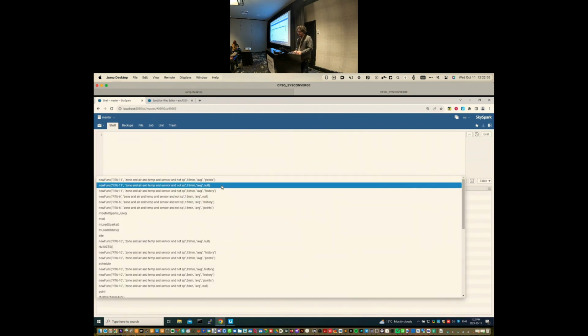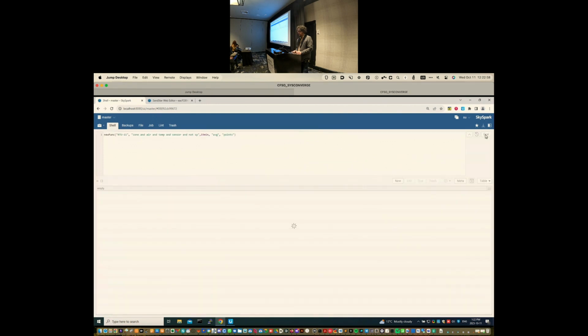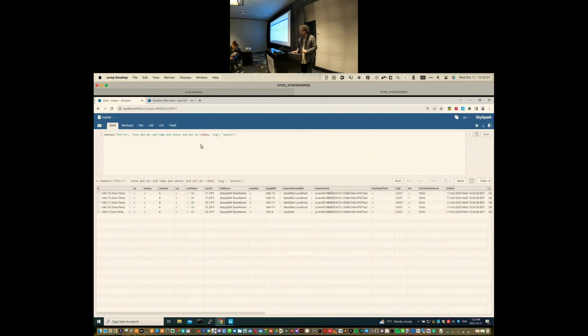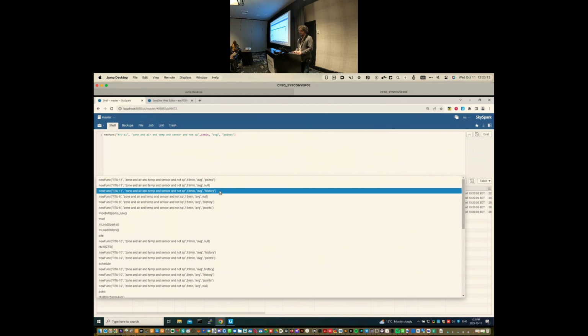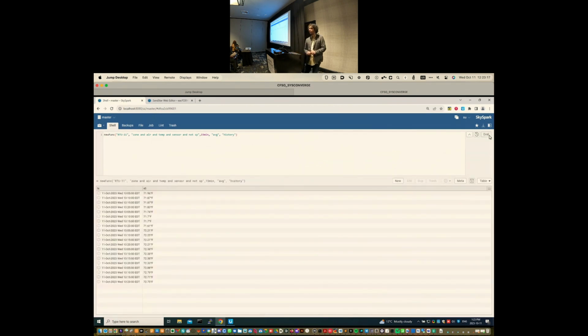We have written an Axon function, and this is a debug version of it. It says, return me the zone air temp sensors that are attached to rooftop unit 11, and it returns the points to us. Just for debugging purposes, I can look at the historical data for the last 15 minutes. You can make these data calls: max, average, and all that.